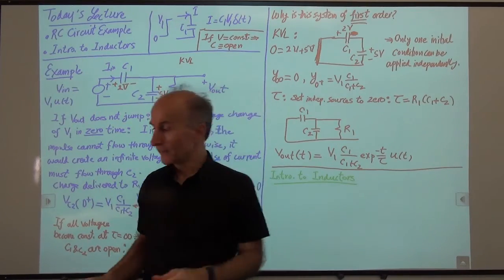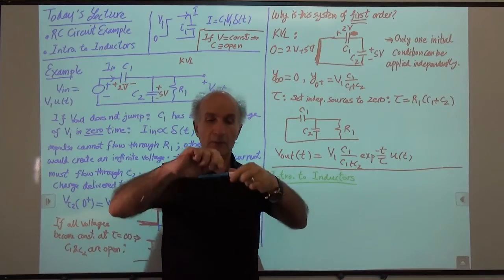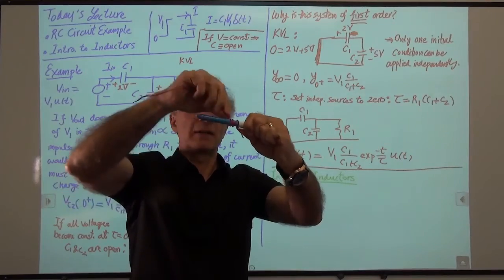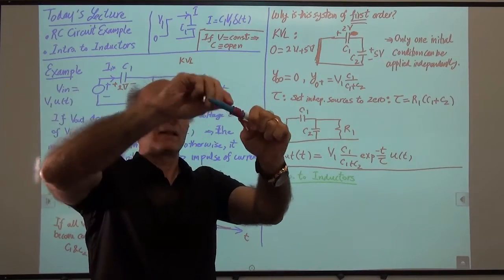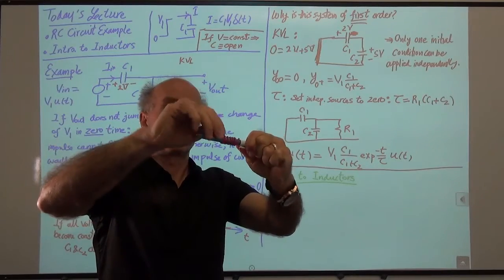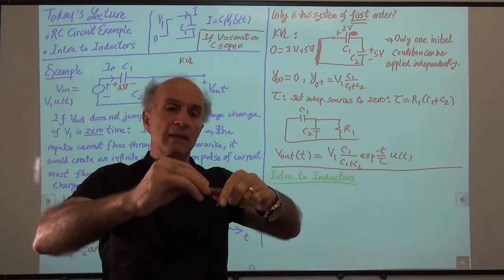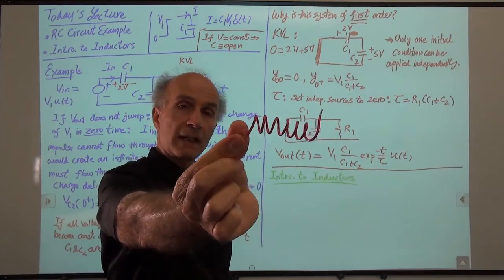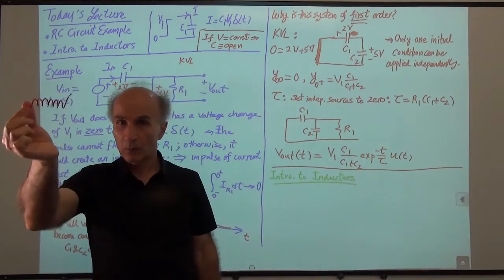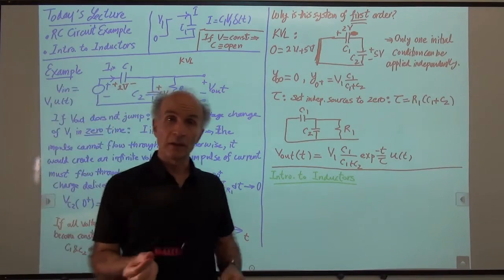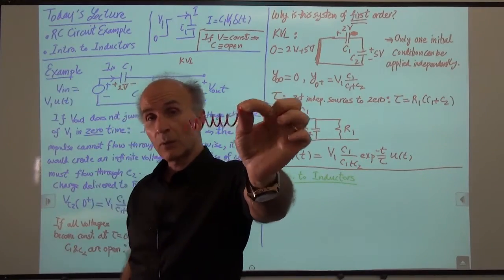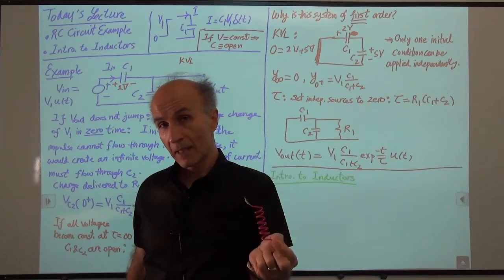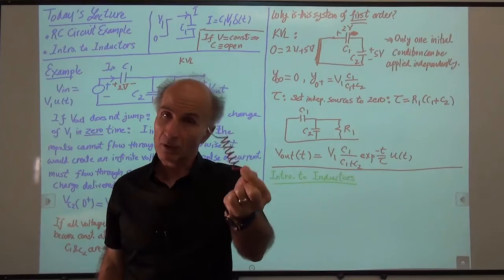But let's take this wire and do something like this. I'm going to take this wire and I'm going to wind it around this pen. All right, I hope you can see what happens here. So we wind it around this pen, and this is what we get. What is this? This is an inductor. So what happened? We had a piece of wire. It satisfied Ohm's law. But by just reshaping this wire, we created a device that doesn't satisfy Ohm's law. And that's the fascinating thing about this and about magnetism, because this all relates to magnetism.